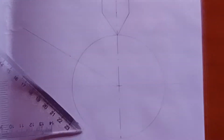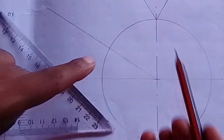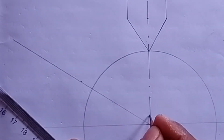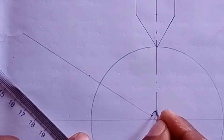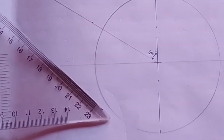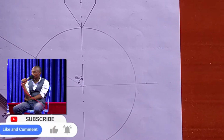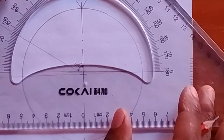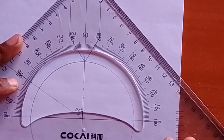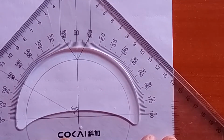Then after you have done and identified those things, you must divide this angle. You see this angle, from here to here, this is 60 degrees, and that's what we are calling the outstroke. Divide it again, by 6 times. Again, put your protractor where you should be putting it at that particular point. Then after you've put your protractor at that point, aligned like that, measure 10 degrees.